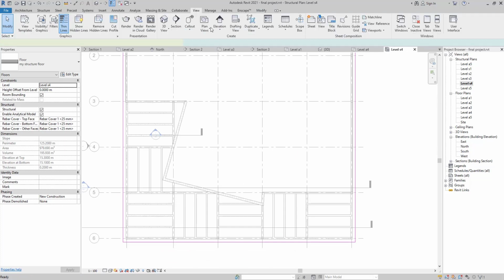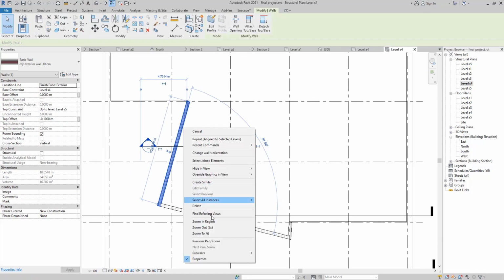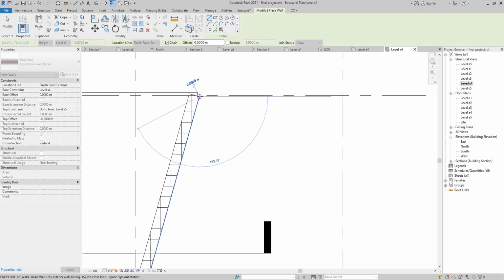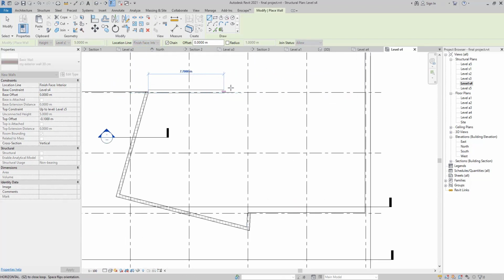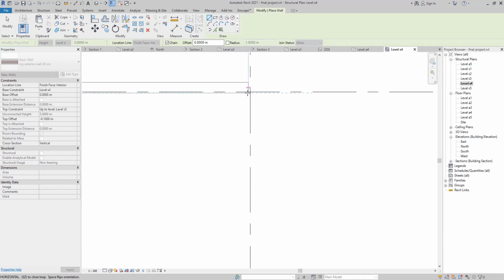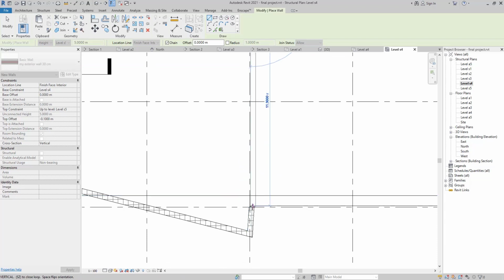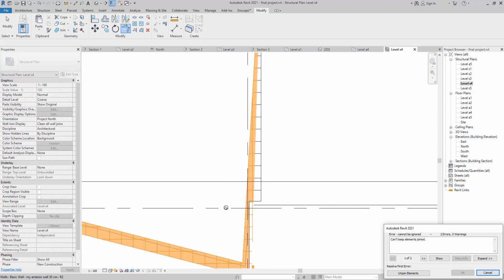But first we need to draw the rest of the wall. So we click on one of the walls, and after that create similar, and then we start exterior wall 30, it's a similar wall, and then we are just going to design it using the interior side, and we will design it until this grid, and then here, after that we use the trim.